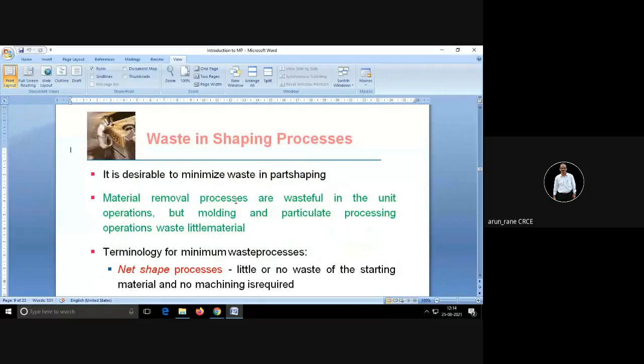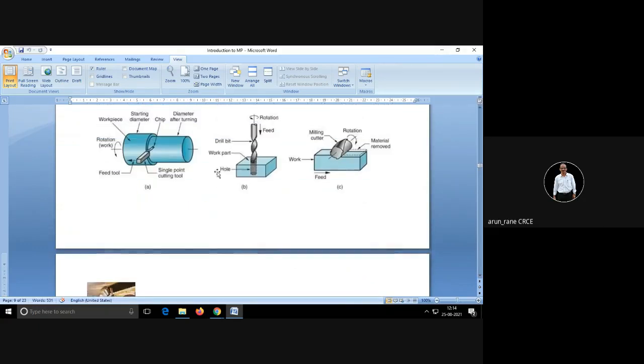It is always good practice to minimize waste when you are using a shaping process, like, say, the lathe. Suppose the diameter to be turned is 20 millimeters, then the raw material you order should be around 22, 2 mm or 3 mm more, or at the most 1 inch diameter, that is 25 mm.